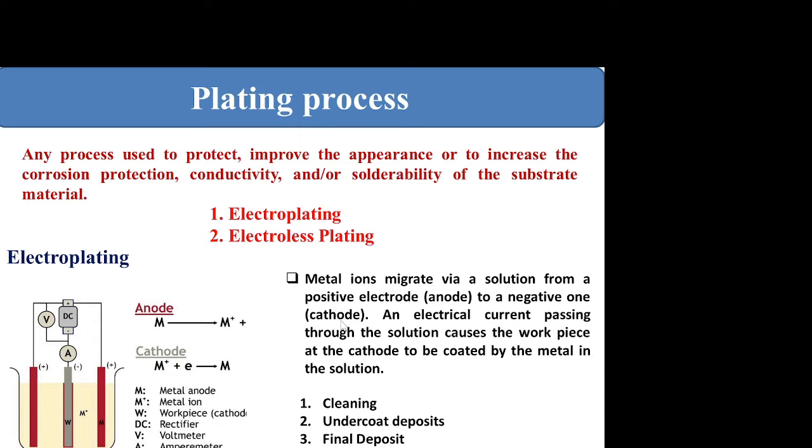Here the bath used in the case of gold plating is potassium cyanide. Similarly, we can coat nickel over iron using nickel sulfate electrolyte, and graphite electrode is made as positive electrode, and the iron workpiece is placed as negative electrode. So nickel, as Ni2+ from solution, can be deposited on the workpiece.